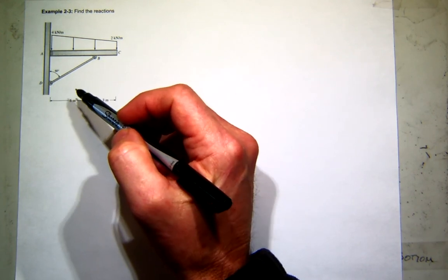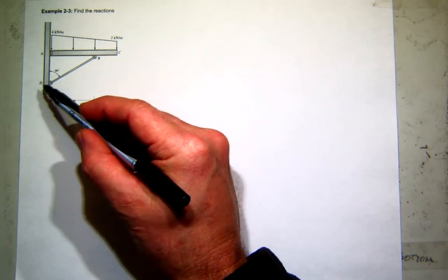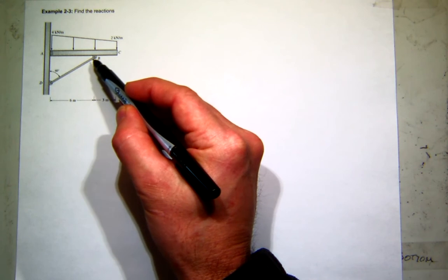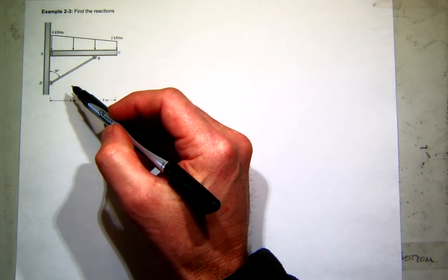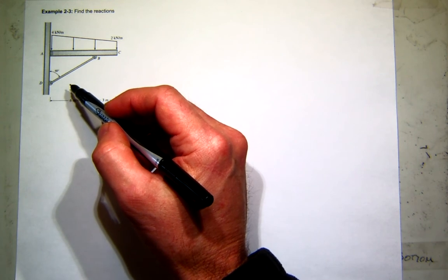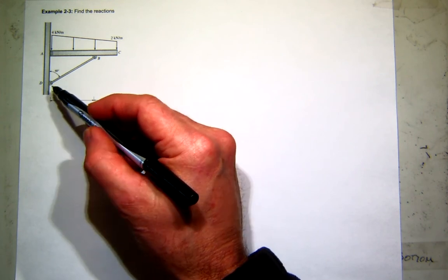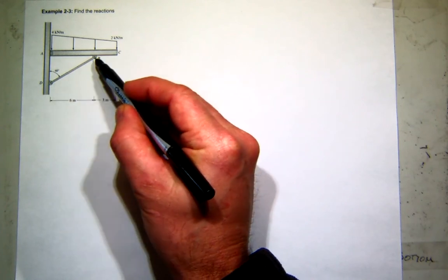It's called a two-force member. What does that mean, two-force member? That means there's only two forces on the member, and they pass through a line of action that connects the two endpoints. Basically, that's just an axial loaded element. We'll talk about that more when we go back and review trusses and do truss analysis. By definition, trusses are composed of these kinds of elements.